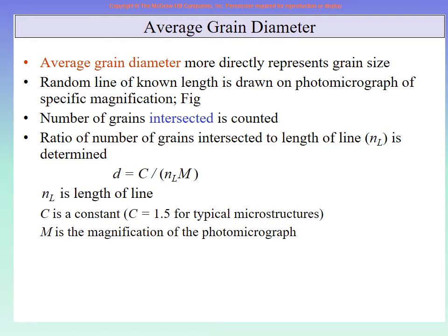But we are taking a very small piece of the material, and we are doing only microscopy in nanometers. Once we do the microscopy, we see the grain structure. From this grain structure, if we can find the average grain diameter, then we can predict that the material property called yield strength will be so much.